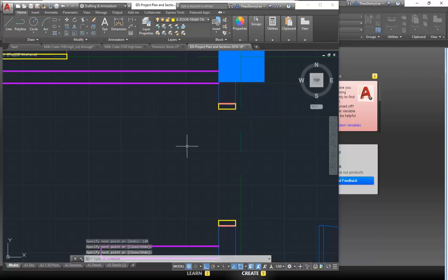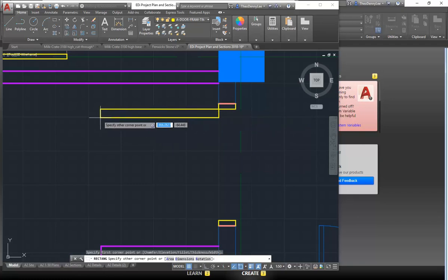So I've got my nice simple door jambs, and then I'm going to draw a rectangle from the corner down to the left, and because it was a 900 opening and we came in either side 40 mil for the door jambs, that means the door must be 820, but we're going to the left, so it's minus 820 to make it go left, comma, and then do you know what standard door thickness should be?